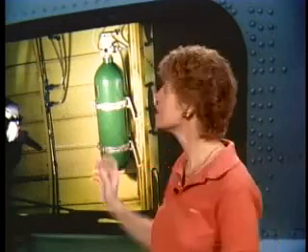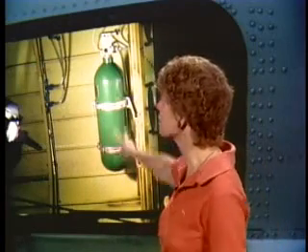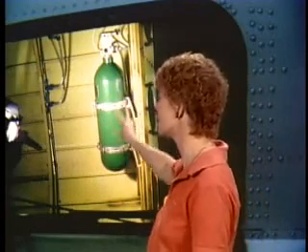Now, when you're working with a built-in oxygen system in an aircraft, in some of those systems, you will have a pressure reducer valve. The whole purpose of the pressure reducer valve in the system is to change the high cylinder pressure, because in the cylinder you've got pretty high oxygen pressures, 1800 psi and so on, down to low pressure for the oxygen system as it goes through the aircraft.